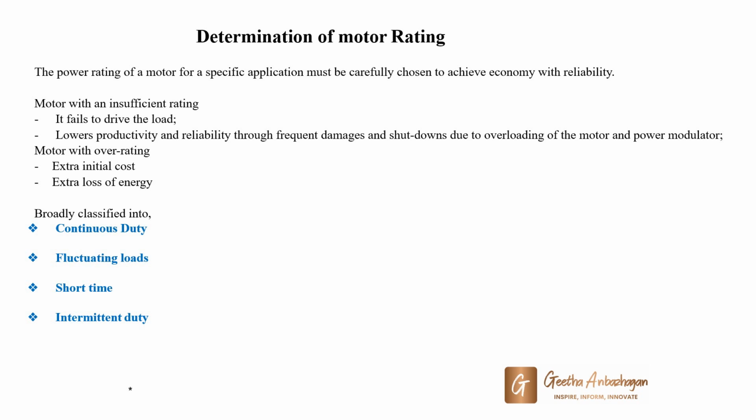Now, consider the other side, using a motor with excessive power. Overrated motors come with a higher upfront price tag. You end up paying more for power capacity that you may not need. Operating an overrated motor at less than its full capacity results in energy inefficiency. It consumes more energy than necessary, leading to increased operational cost.